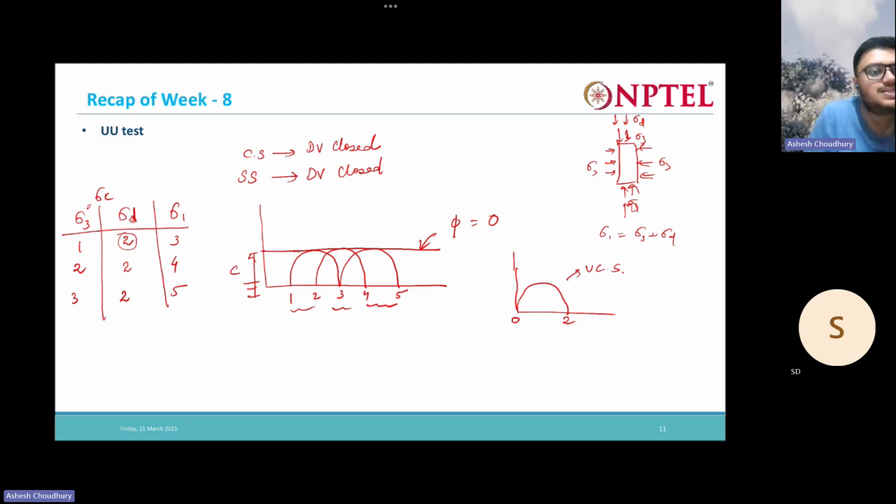Now when you increase sigma 3, the extra increase in load is taken by the pore water. But the soil fails at the same load, 2 only, because the soil can take only that load itself. It cannot take more load.